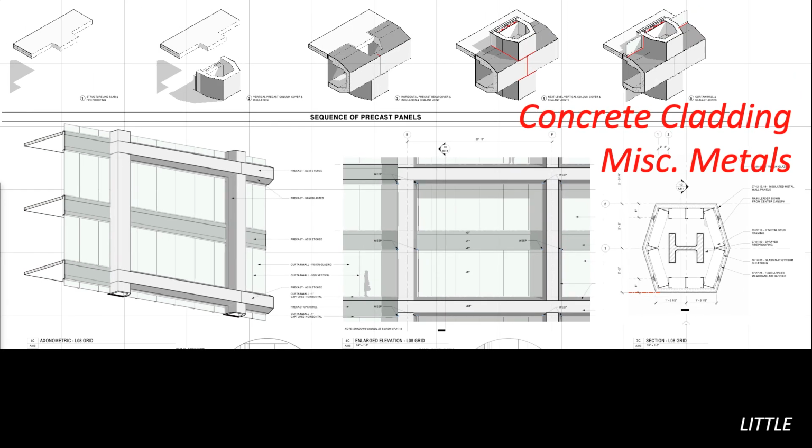This is another detail, and I thought this was useful because oftentimes we'll wish that we could show the structure, but I think at this scale, we really do need to protect steel with fireproofing. But in this case, they used these precast elements. There's lots of fireproofing types, but in this case, they double dutied that the concrete cladding was going to be basically a fire protection for the frame. And so you do get the expression of a frame. It's not a wide flange, but we still get the vertical columns and the horizontal members that are expressed through this covering. And the coverings could be concrete, the coverings could be metal.